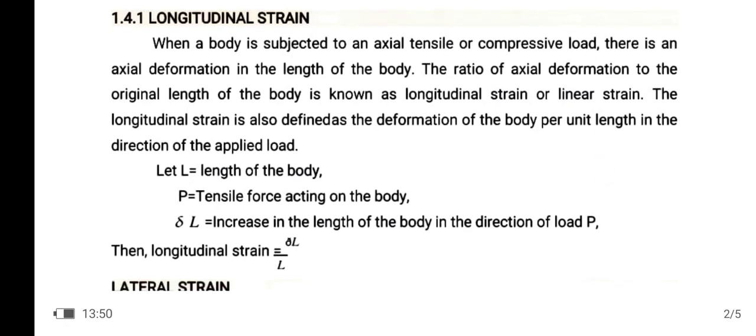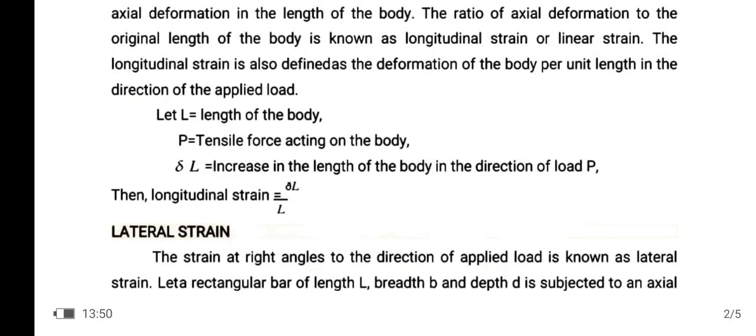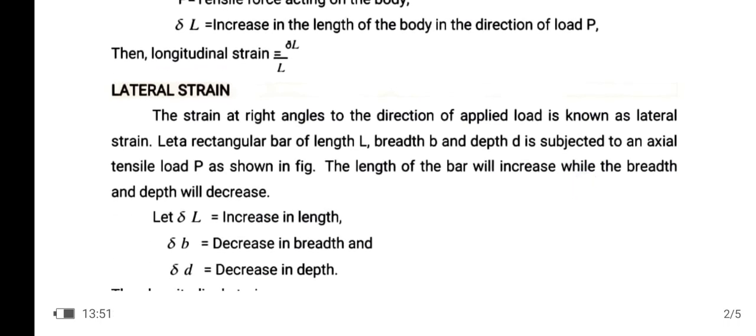L is equal to length of the body and P is equal to tensile force. del L is equal to increase in the length of the body in the direction of load P. Therefore, the longitudinal strain is equal to change in length divided by original length. Then next topic, lateral strain.